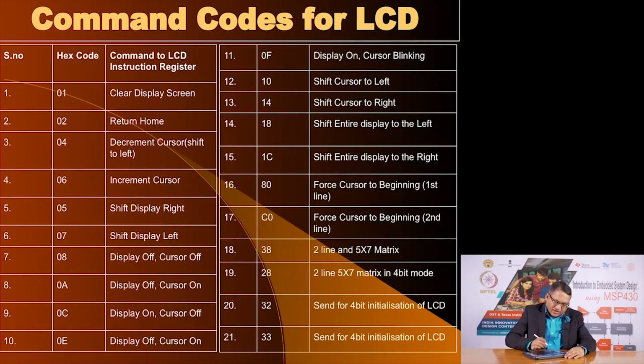Okay, so these are the commands. What commands can you send? You can send a command to clear the display. You can send a command to return to home. Home means the initial position of the cursor. You can increment or decrement the cursor. You can go forward or you can go backward and so on. So there are about 20-25 commands here, as you see, 21 commands which allow you to interact with the LCD controller. Some of these commands we will see when we do an exercise. Let us go towards that.